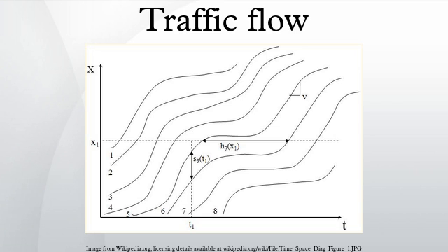Classical traffic flow theories: the generally accepted classical fundamentals and methodologies of traffic and transportation theory are as follows. The Lighthill-Whitham-Richards model introduced in 1955-1956. Daganzo introduced a cell transmission model that is consistent with the LWR model. A traffic flow instability that causes a growing wave of a local reduction of the vehicle speed.